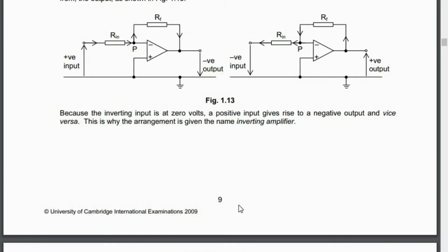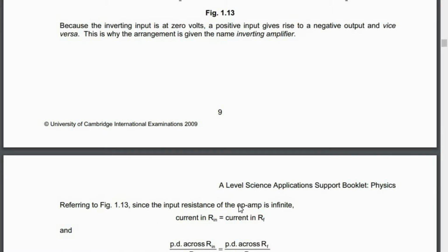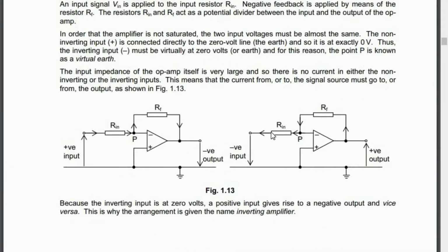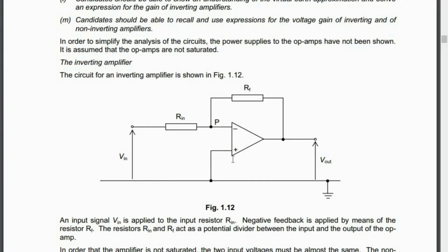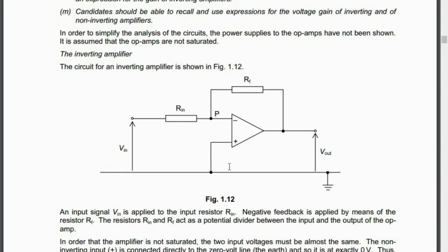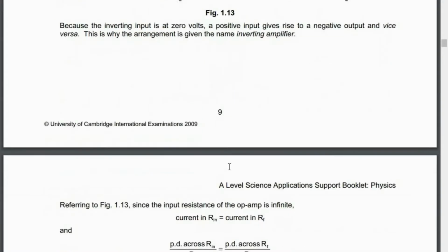There is no positive feedback loop. If you put positive feedback here, the thing will go even crazier: whatever noise there is, it will multiply and amplify the noise, and the system will become more unstable. That will as a result decrease the frequencies over which it works nicely. Then won't it work badly? So we don't want that. So we always connect the feedback loop to the inverting input. Yes, it's always connected to the inverting input. Always. Only that gives negative feedback. If you connect it to the non-inverting input, you're going to get positive feedback, which makes the system keep growing. It makes it worse. Clear?